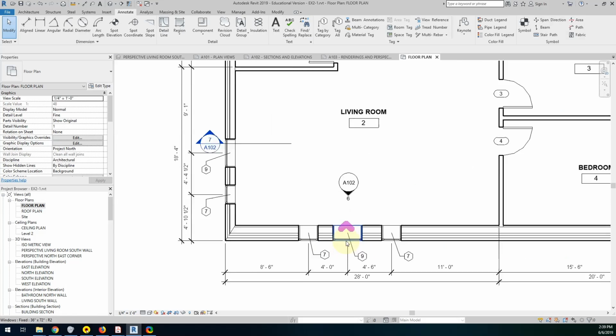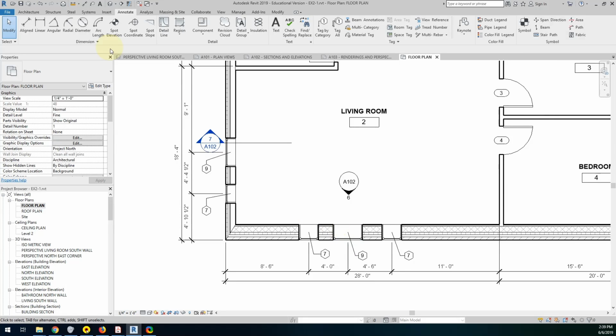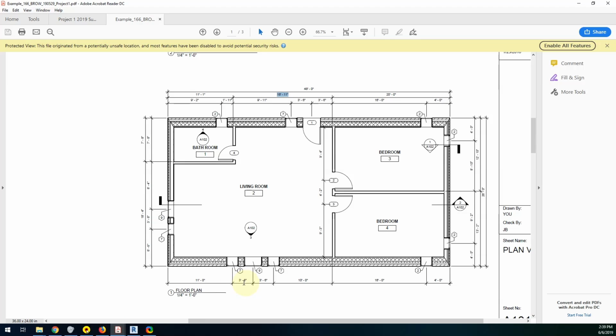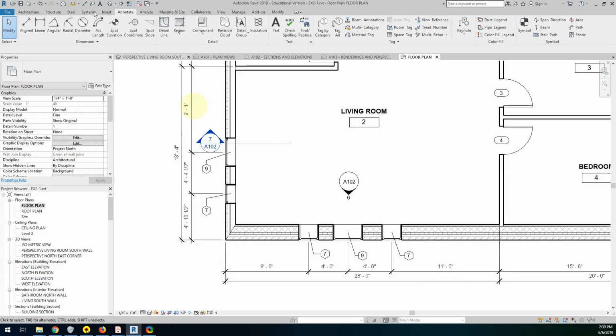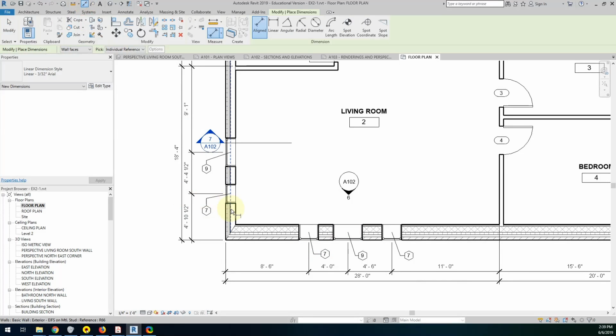Now let's start with these living room windows. I'll show you a little trick here. So we want the windows to be 3'6" from either side, and then we want it to be centered in the room. Let's say you didn't know what these dimensions were at first when you're planning this out. So we can use our dimension tool. Go to the center, the wall face, the center of the window, and the far wall face. And then you'll see this little EQ symbol above the 2 dimensions. If I click that, it'll center the window.